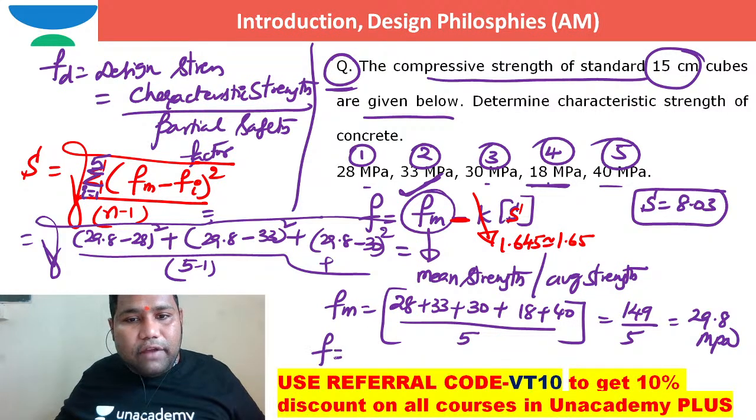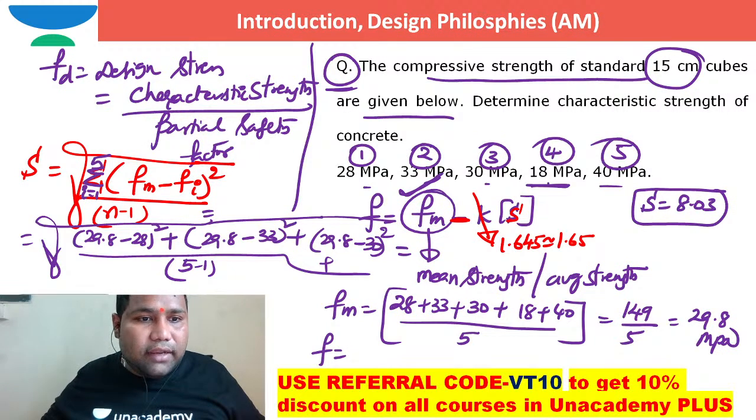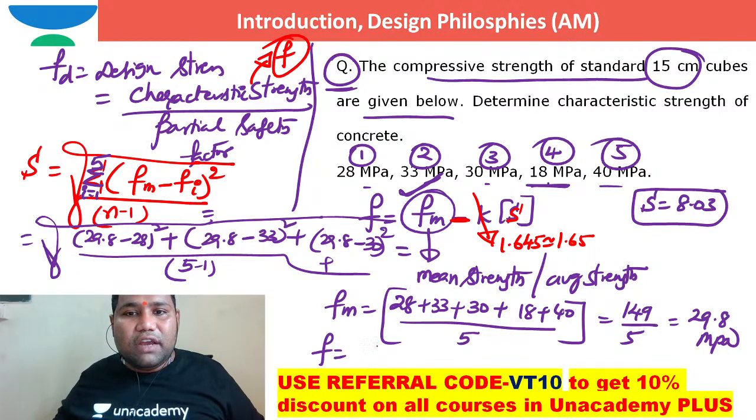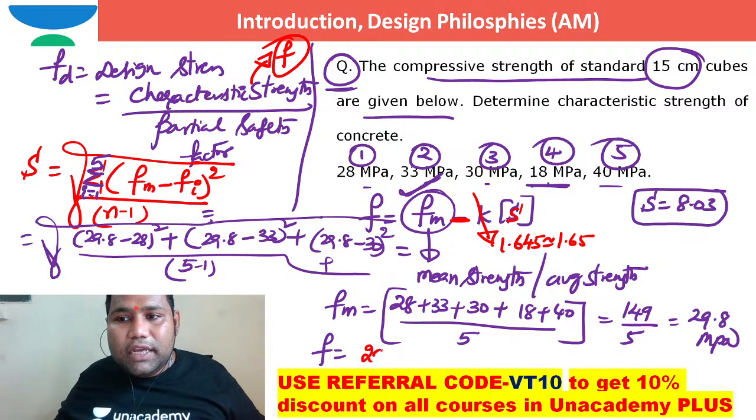So coming to this value of F, which is nothing but the characteristic strength. We can write the characteristic strength as F. F is equal to Fm, which is 29.8, minus 1.65 times the standard deviation. The standard deviation is 8.03.